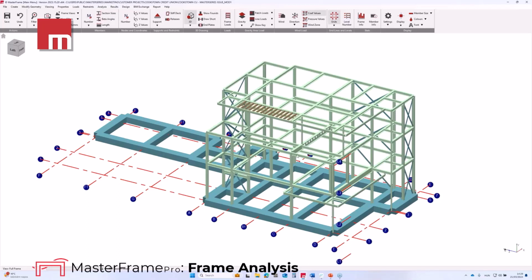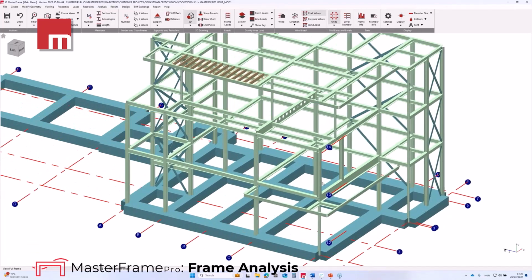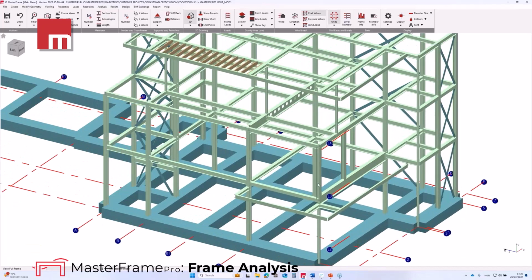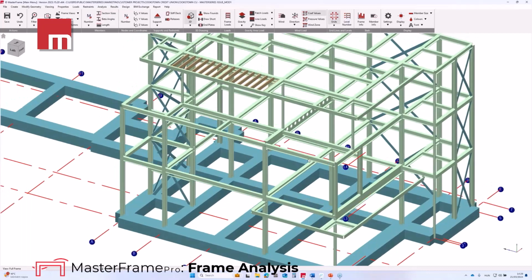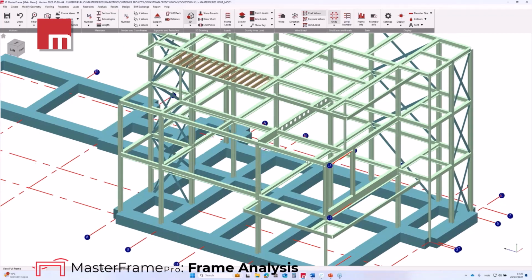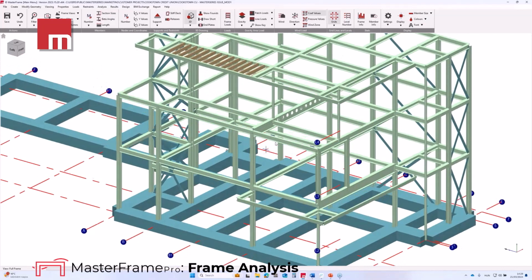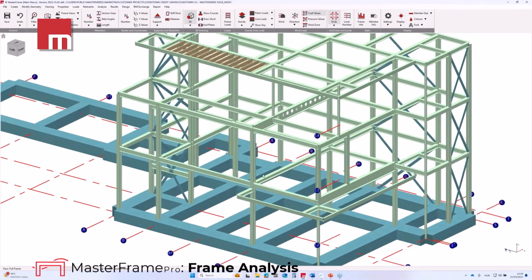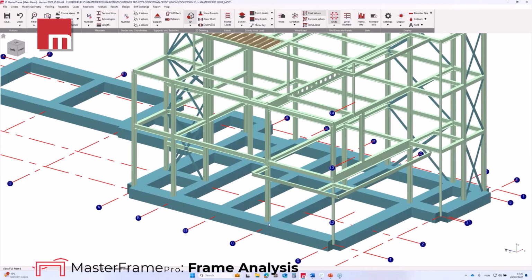The beams and the columns are mainly S355 standard UB and UC hot rolled cross sections. However, they used CHS and hollow sections where the architectural concept required. We also have a bigger UB with several circular web openings on the second floor. The ground beams are simple rectangular concrete members.